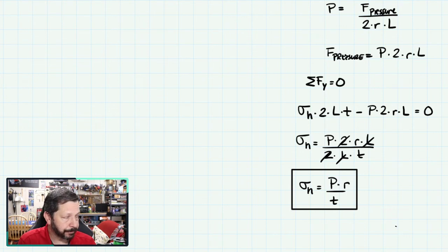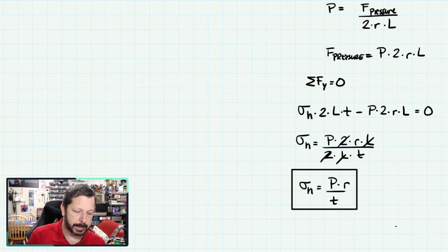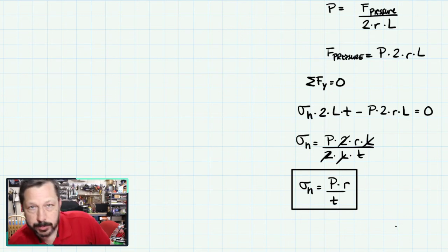Now again, the end caps on these cylindrical ones do have an effect on pressures that you would deal with. You can combine the longitudinal and the hoop stress together to get some stress at an angle. You might want to do that if you've got a weld seam that goes around here at an angle and you want to find the stress on that weld or something like that. None of those things are things we're going to do in this course.